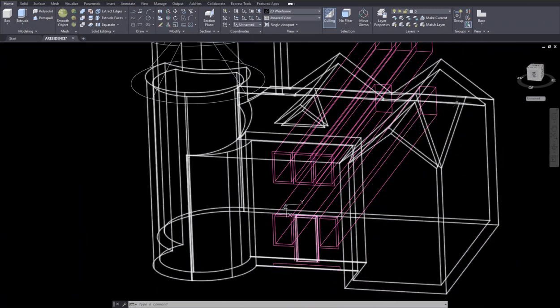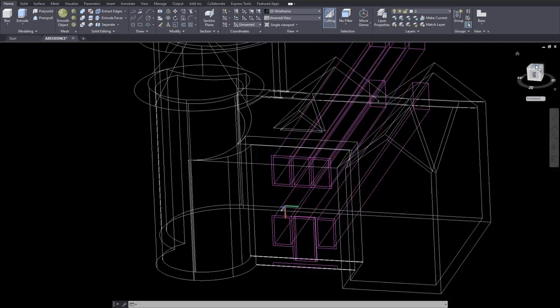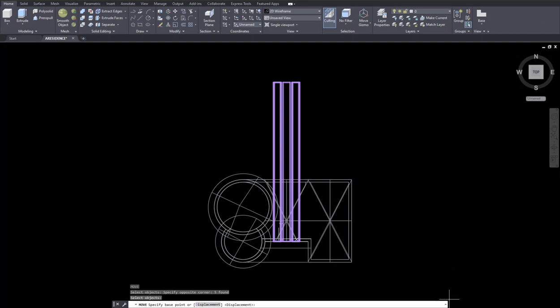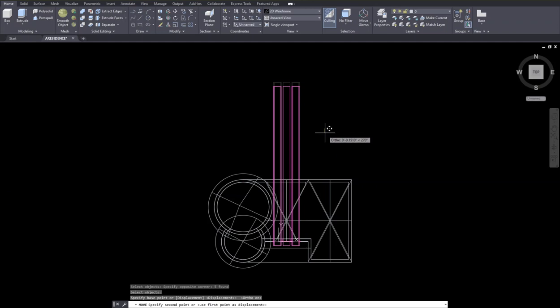So I can go to top view, okay? And type UCS, enter, and view option. I change that. And now move command, and that extrusion needs to be a couple of inches down with the ortho mode on. So what I did is simply move it down a little bit, not too much, a little bit, okay?